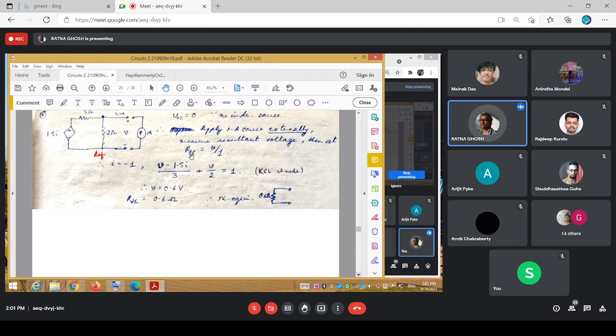Another reason is that you need not think of it in that sense because it is a dead network anyway. You know that the whole objective of doing this is to find out an equivalent resistance, looking back resistance or the Thevenin resistance. Had there been any independent source here, you would have moved forward to find out the open circuit voltage or the short circuit current, right?